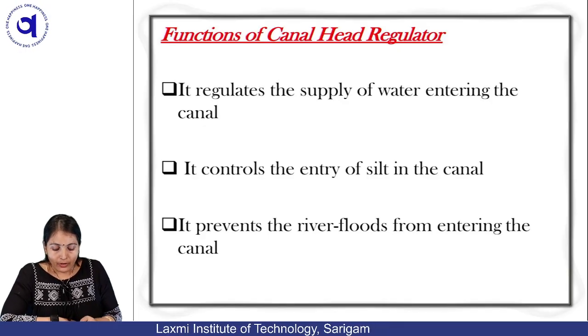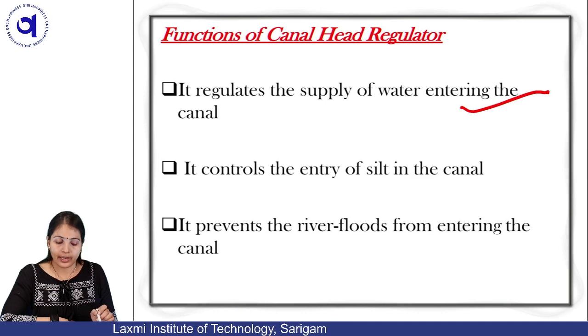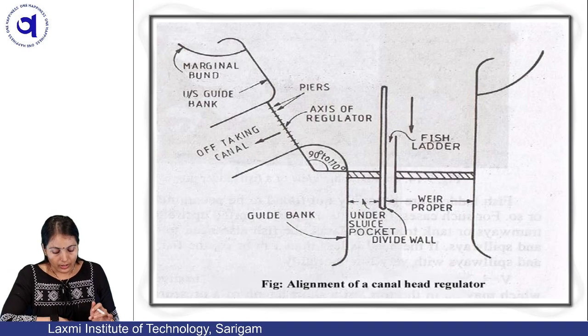Okay. Function of this canal head regulator. What's the function of this? It regulates the supply of water entering the canals. It controls the entry of silt also, and it prevents river flood from entering the canals.